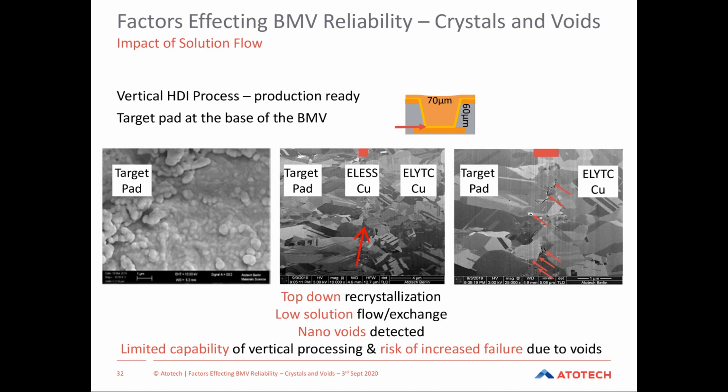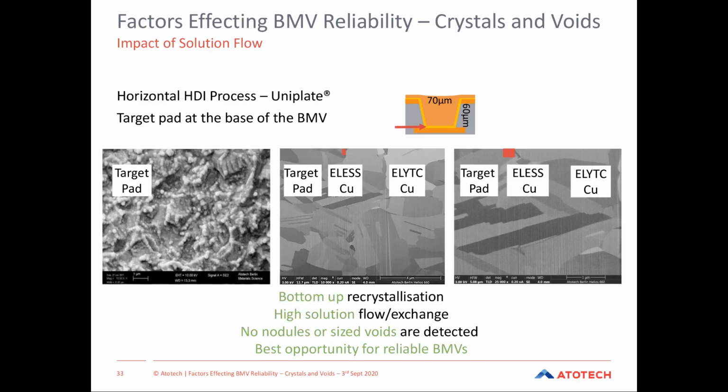So while there are a lot of microvias made vertically and they are reliable, we are definitely concerned about the capability limitations of vertical processing because we're seeing more vias where there are breaks in crystallography and there are breaks in voids. So we anticipate increased failure risks in these crystal structures as well.